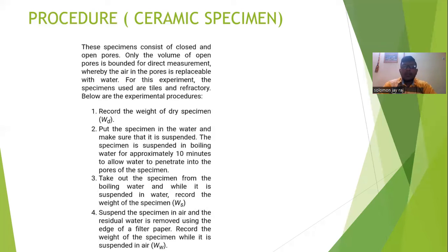So first we record the weight of the dry specimen, then put the specimen into the water and make sure that it is suspended. The specimen is suspended in boiling water for approximately 10 minutes to allow the water to penetrate into the pores of the specimen.